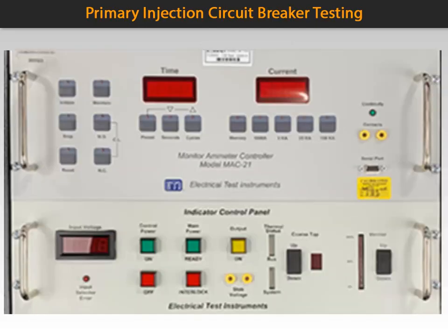Let's take a look at the front panel of the control board to help familiarize us with some of the functions. 2 LED displays are noticeable right from the start. The one on the left is a time display. It indicates the elapsed time of the current pulse. The touch keys below set up the display readout. To the right is the current display. This displays the true RMS output current of the test set. It can also be put into memory mode to display prior readings. The touch keys below set up the range of the display.